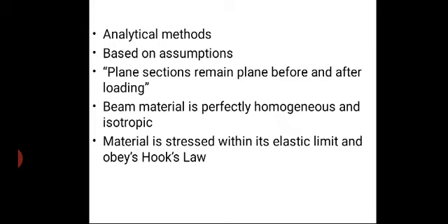Such assumptions are, first, plane sections remain plane before and after loading; second, the beam material or any material is perfectly homogeneous and isotropic; and third, the material is stressed within the elastic limit and obeys Hooke's law.